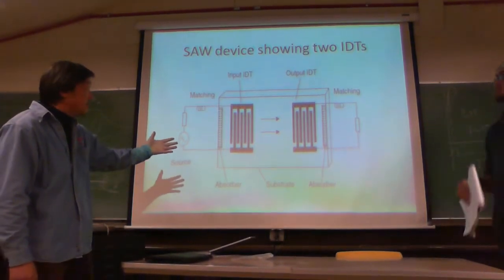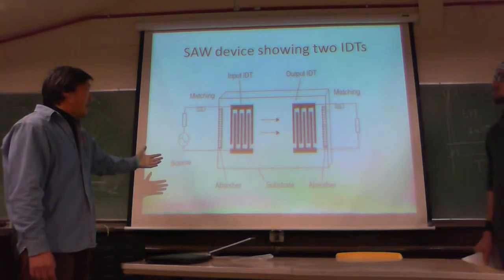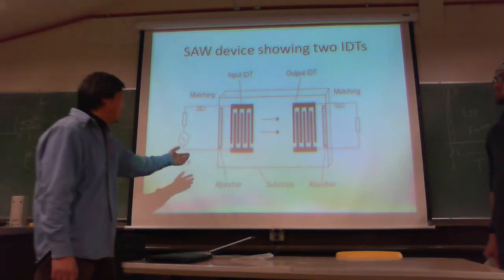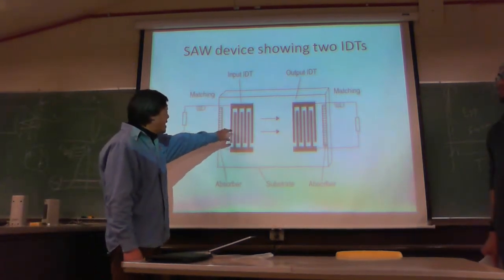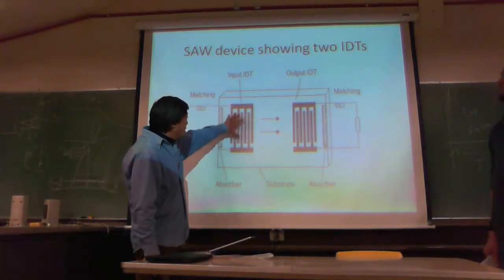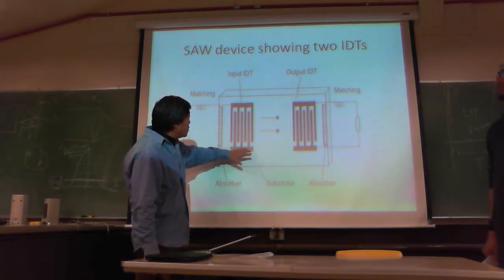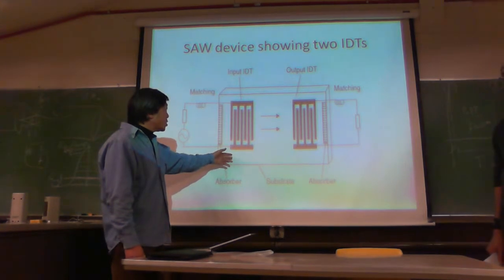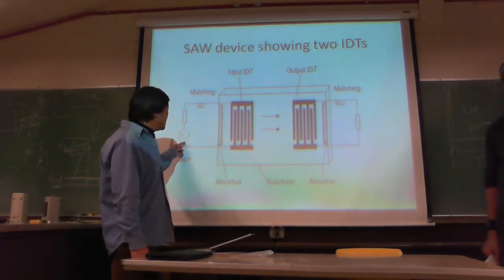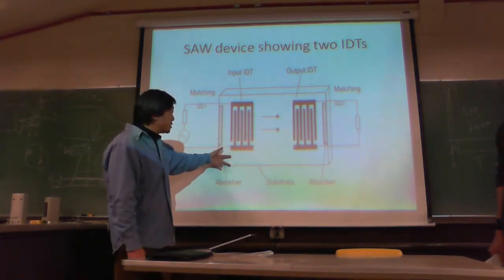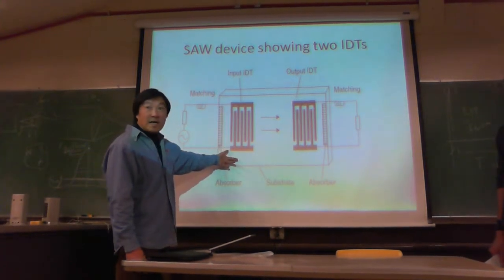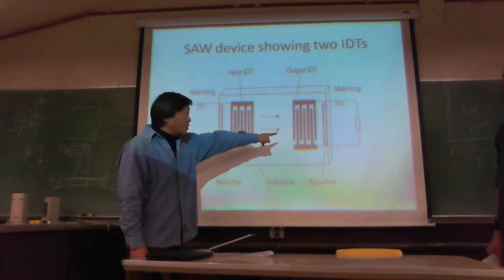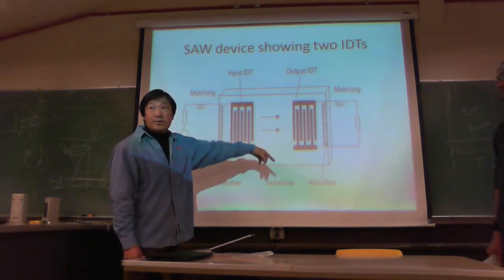This invention allowed use of the piezoelectric effect of the crystal, and by embedding the electrodes into the crystal using lithographic printing, you can use an electrical signal to produce an acoustic wave and pick it up on the other side using the same kind of transducer.